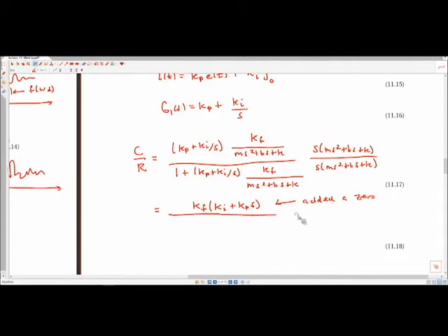And now, instead of a second order system like we always had before, we have a third order system. So no longer, just like with the proportional derivative, that was not a pure second order underdamped system. Same with this case, not a pure second order underdamped system. We have an extra 0, we have an extra pole, which has influences.